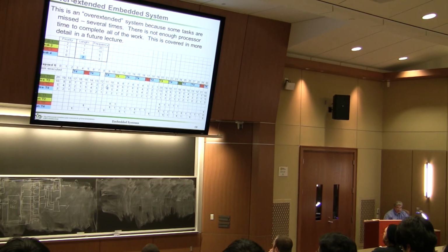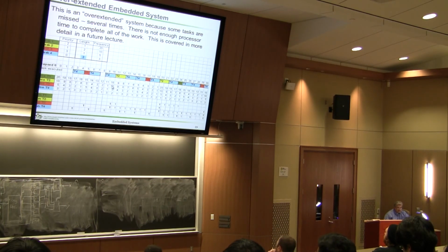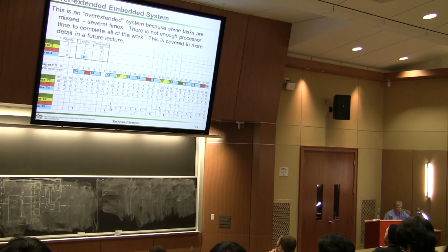So every time it goes from 1 to 0, you reset it to the frequency. In this case, the frequency is 10. And then you set the variable here to 1. And that is done in the scheduler, for every task.